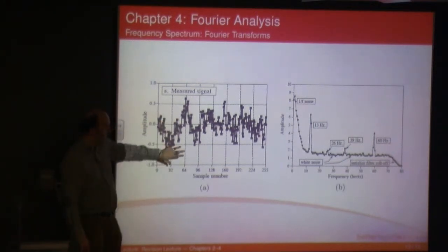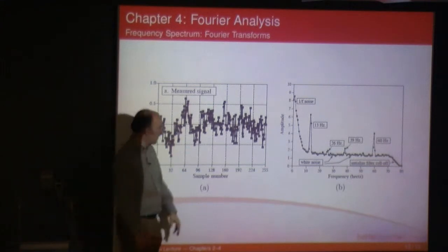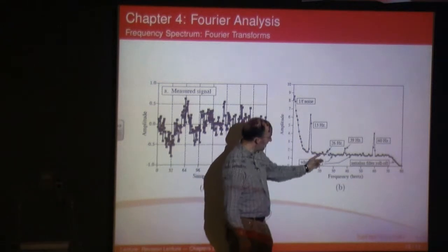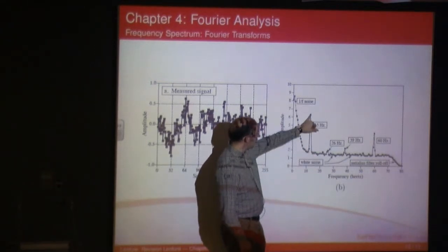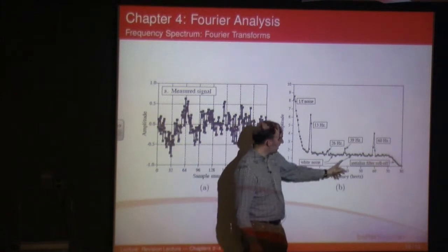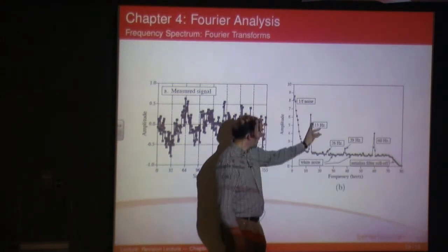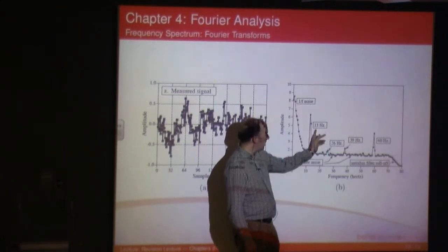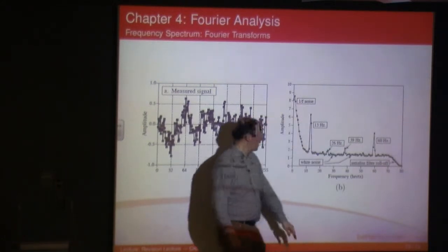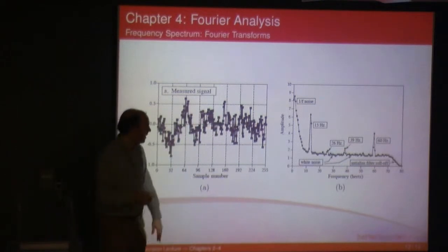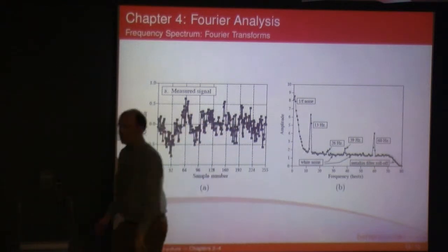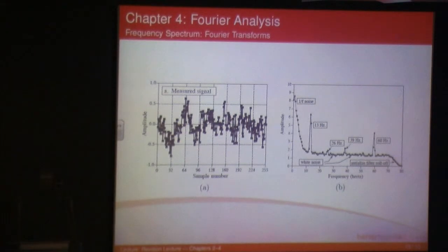What you can do is you can plug that through the computer to get the Fourier transform, and you get a signal that looks like this. You've got a bit of noise, okay, but you can see quite clearly there's a peak here at 13, 26, 39, and 60 hertz. And so that's the fundamental frequency. That'd be the second harmonic and the third harmonic, okay, and then that will be due to the mains supply that's being used, okay. But you can see quite clearly that you don't want to excite your system at 13 hertz. Because you get this massive peak in frequency, and that's your fundamental.